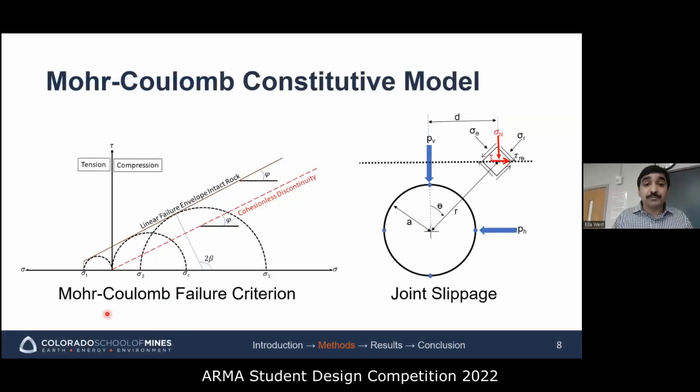Used for material shear. Which is also the case with the weak rocks under low confinement. For given cases, the strength of rock mass is characterized by cohesion and friction angle, using major and minor compressive stresses.